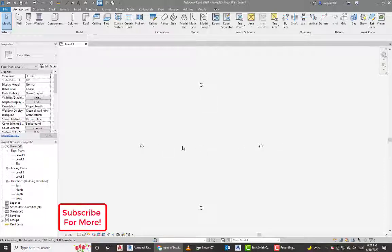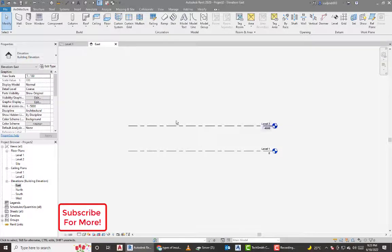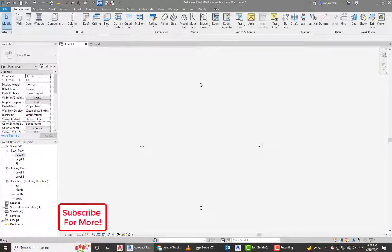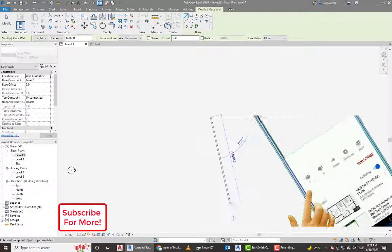So let's move on. Before you can draw an insulation, you have to first check your levels. So we have the level 1 and we have the level 2. This is an Autodesk template which comes with a metric. So I'll come to my level 1 here and pick my wall from the architecture tab. So I'm going to draw some wall here like this.